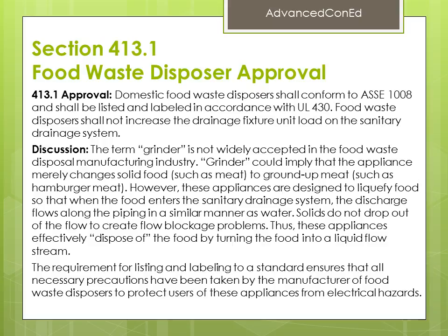Section 413.1 Food Waste Disposer Approval. 413.1 Approval. Domestic food waste disposers shall conform to ASSE 1008 and shall be listed and labeled in accordance with UL 430. Food waste disposers shall not increase the drainage fixture unit load on the sanitary drainage system.